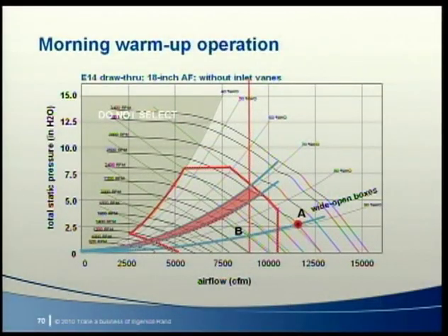Some fans include piezo-based inlet flow measuring devices that do not cause turbulence or acoustic problems. With these sensors, another control approach can be considered. Again, with the boxes wide open and the duct pressure control disabled, the supply fan speed can be modulated to maintain fan airflow at 9,000 CFM. The selected fan can certainly handle this, and the heat exchanger gets plenty of airflow.